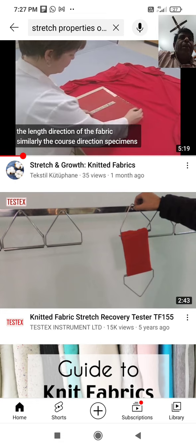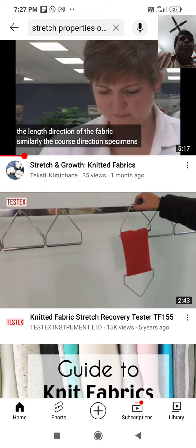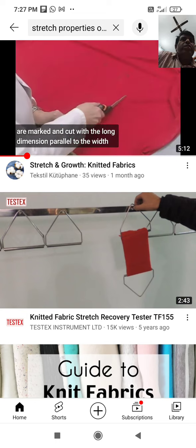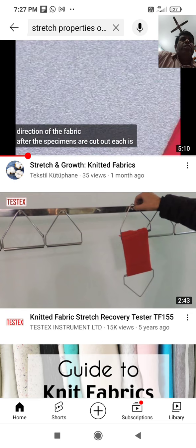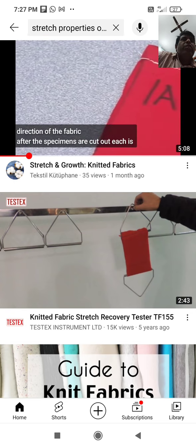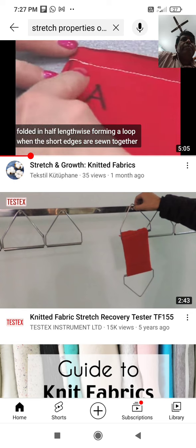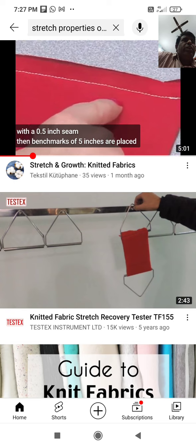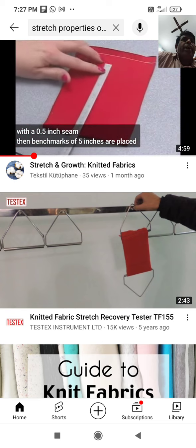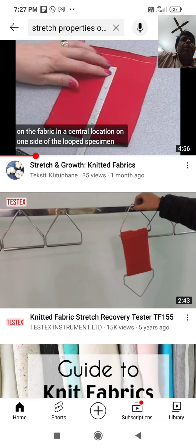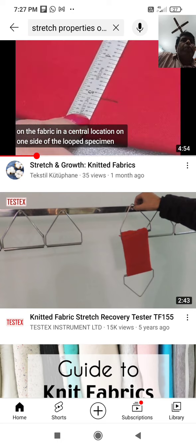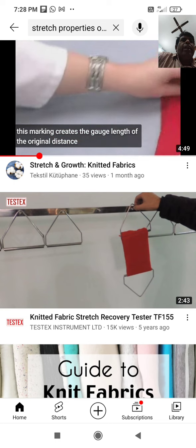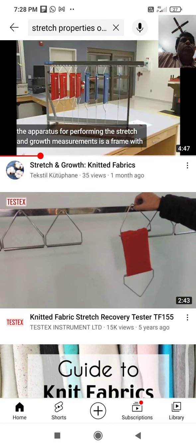And laminated fabric is a layered fabric structure wherein a face or outer fabric is joined to a continuous sheet material such as polyurethane foam in such a way that the identity of the continuous sheet material is retained. And this in turn, but not always, is joined on the back with a backing fabric such as tricot. So it has defined the difference between bonded fabrics and laminated fabrics.